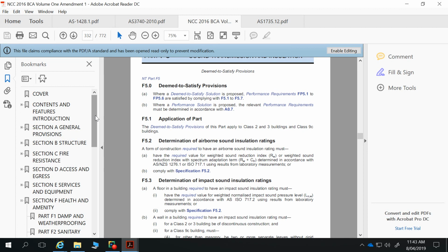That 125mm sphere just keeps popping up everywhere. So it pops up once again in relation to balustrades. That 125mm sphere can't pass between balusters in the balustrades. And then we have heights of our balustrade adjacent a stair, which is 865, transitioning to 1 metre high above a balcony or a walkway, etc. So anywhere where you can fall for more than a metre, you've got to have a metre high protection.